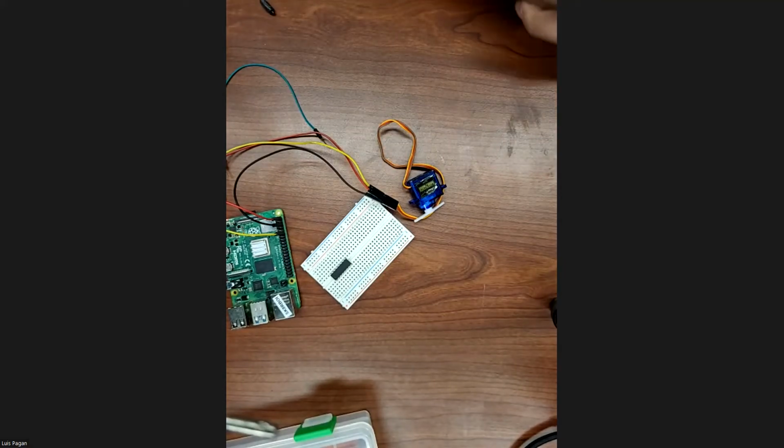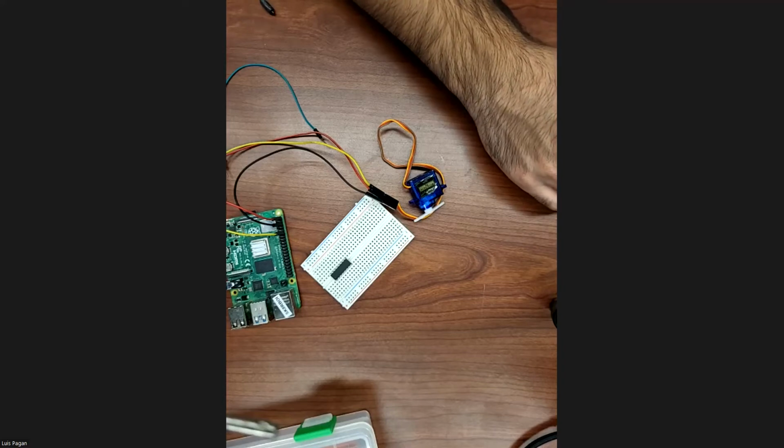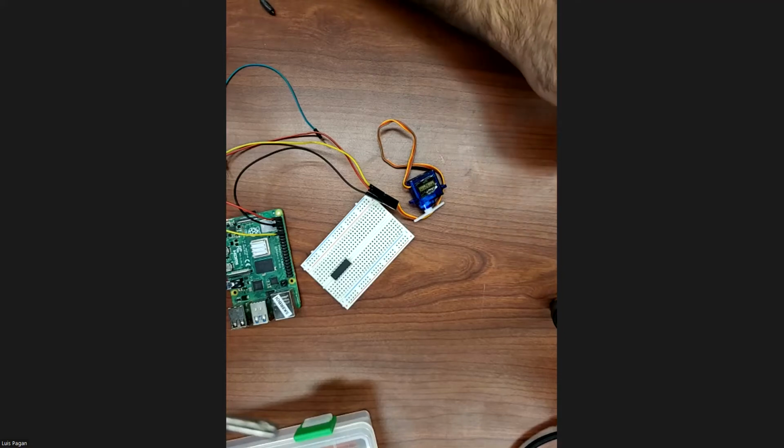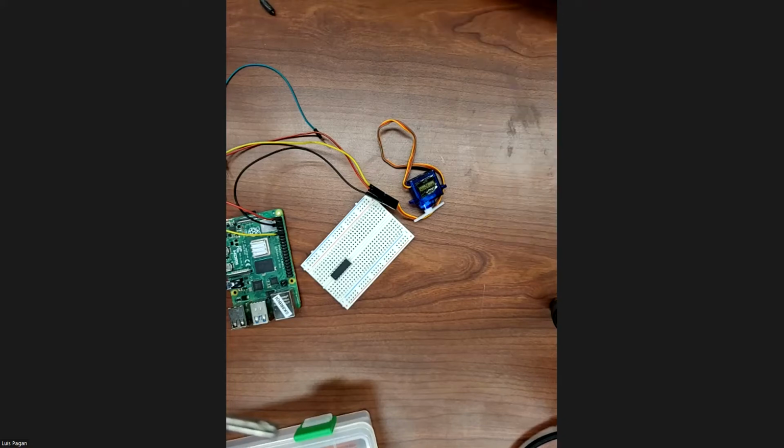The only thing is, let's say you are controlling multiple devices, be conscious that you only have 4 PWM pins. So if you want to do the maximum combination of motors, you can have a total of 4 servos that you can individually control. You can also have two of them set to the same pin. You can connect them together so that they move at the same time, and that'll allow you to use less PWM pins.